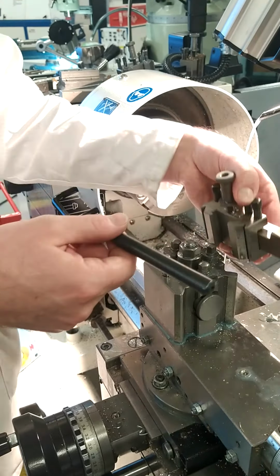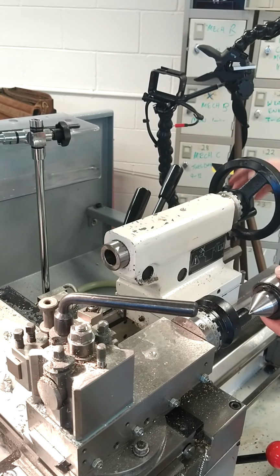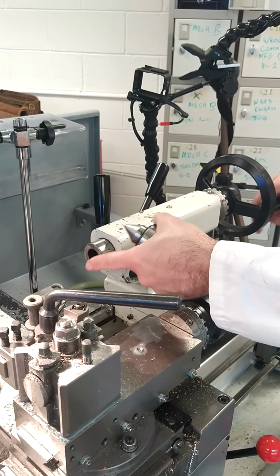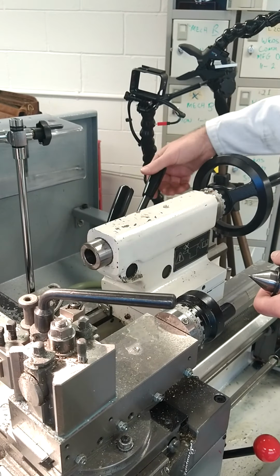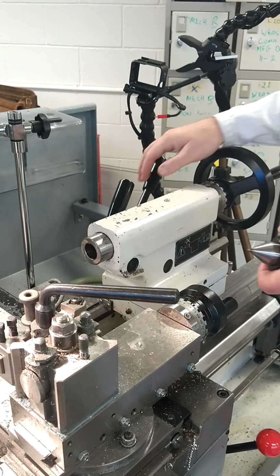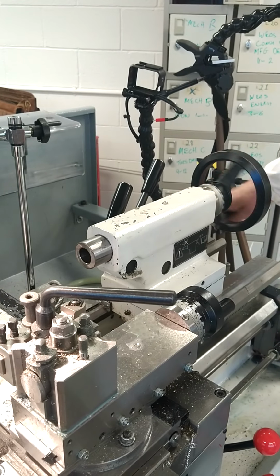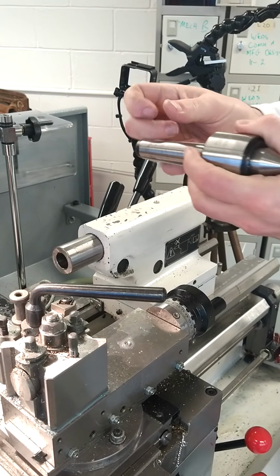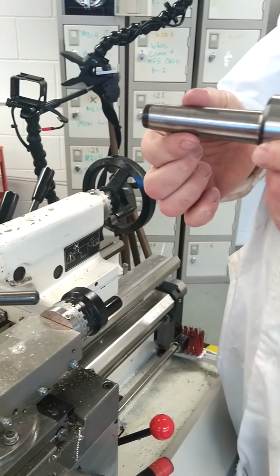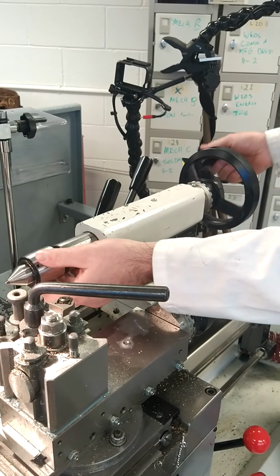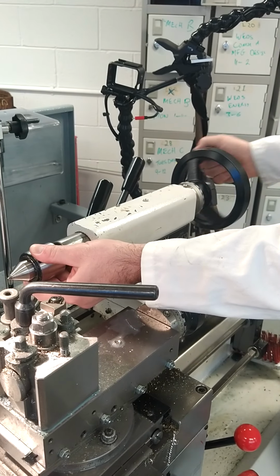So to pop that in, this is what's called the tailstock. This is the tailstock handle at the back. This is the quill lock, which stops you from drilling, so you're going to leave that open. And this is the lock used when you want to drill. To put in the tool, you need to wind forward a distance between 50 and 60 millimeters, because this is a Morse taper fit into the tailstock. It slots in, and to remove it at any stage, you just wind it back and it will pop out.